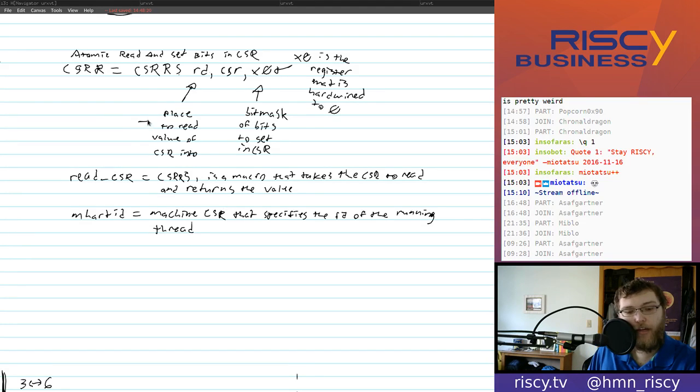And also, this, I believe, is technically a register, a general purpose register. Like we had that temp variable with the CSR stuff that we were looking at yesterday in the inline assembly. We created a temp variable in C, and then we did some inline assembly that referenced that variable to get a value from the machine instruction into that variable. But technically, I believe what that variable boils down to in assembly is it's actually put in a general purpose register. And then this instruction is referring to an actual register.